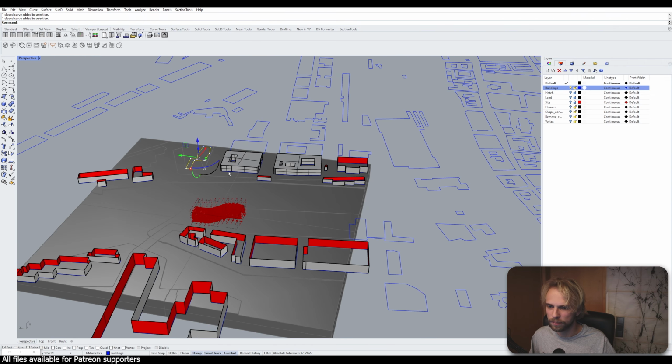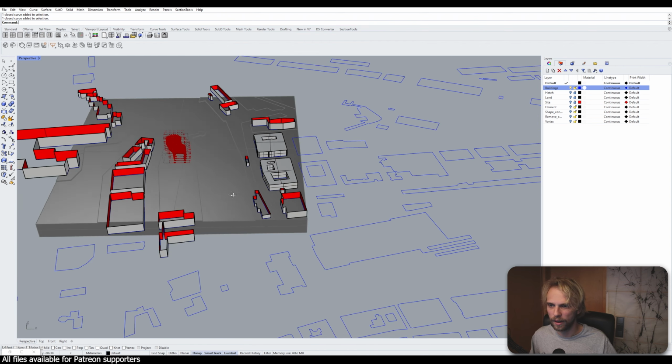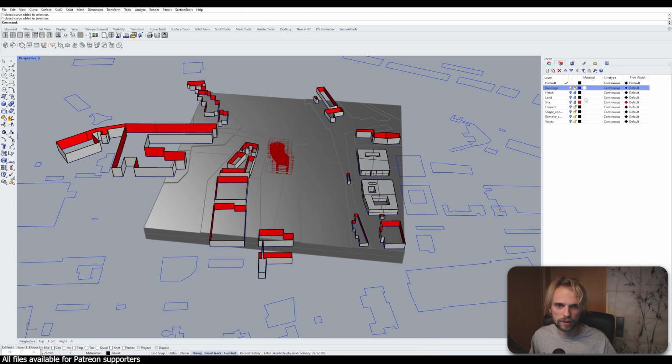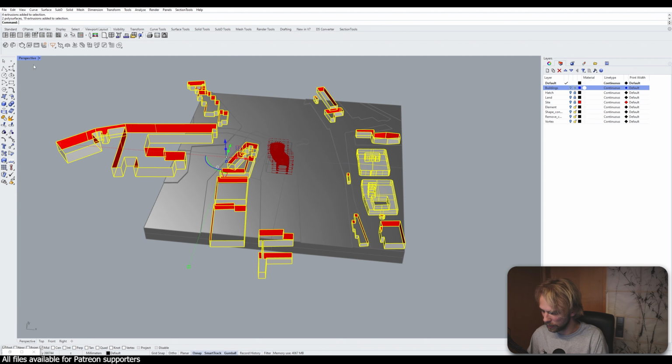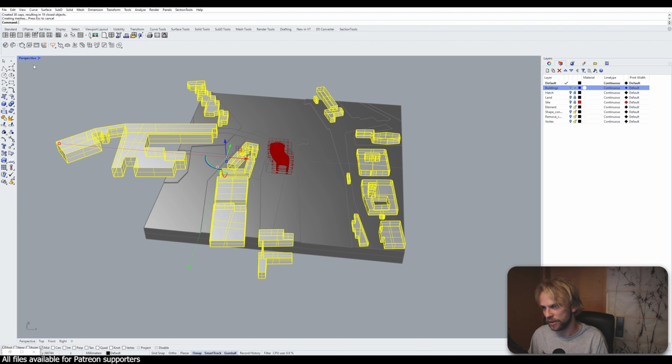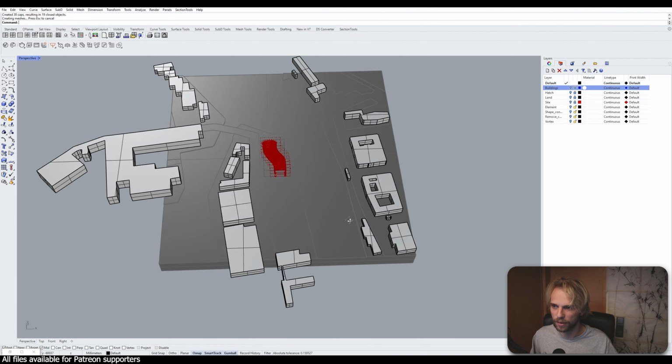And last one, well, almost the last one. Let's say these two. These two are gonna be like 16. Okay, so we have ourselves, I'm hiding the curves immediately. So we have ourselves some buildings. Some of them are closed, some of them are open. So I'm just going to select all of them and just say Boolean. Not Boolean, sorry, cap. Just cap to fill them up.